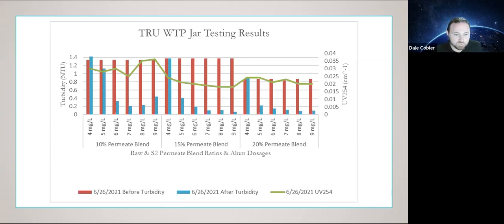If a coagulant is effectively working, then we would expect to see a decrease in turbidity values as more of it is added to the water until it reaches a maximum removal potential. Improper alum dosing can result in flocculant not settling, in which case we would expect to see higher turbidities.